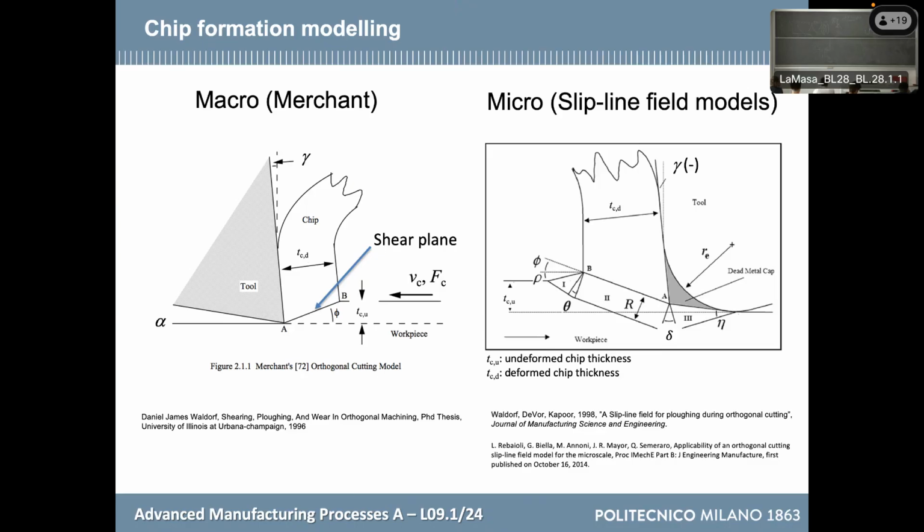And if you look at this, it seems that the material has created its own cutter by putting there some material that at the end is creating a couple of surfaces along which the chip will really flow, like it happens in extrusion. And a model like this considers that there are chunks or portions of material that are sliding along some planes. This plane is the shear plane, like it exists here, but there are also other planes. So this makes this theory complex.